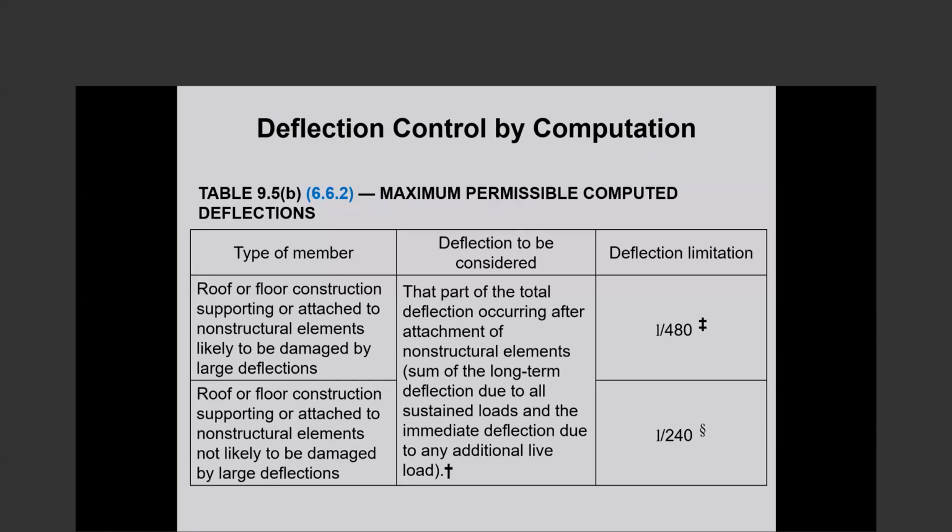So as soon as you attach the non-structural elements, there will be immediate deflection due to the additional loads. And so you take that plus the long-term deflection due to all sustained loads. Sustained loads will be dead loads, could be superimposed dead loads, so some of the superimposed live load, whatever is sustained, the long-term deflection due to that.